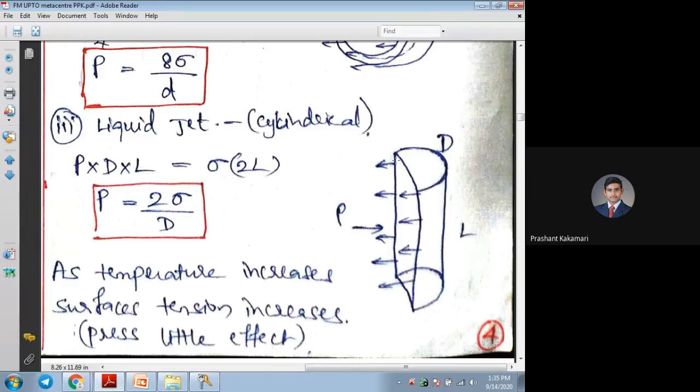You see the tensile force is acting on this length, diameter D, again throughout the height L, and again here D. Okay, pressure. For pressure we are taking the projected area. What is the area of this projected part where the tensile forces are acting? Because I am talking about tensile forces only where the liquid is in contact. So it is in contact with the liquid only on this area, not on the other area. The other area was connected with the pipe surface, or with the surface of the well in which the water is stored. Okay, so that area we are not focusing on. We are focusing on the area which is in contact with the same liquid or same material.